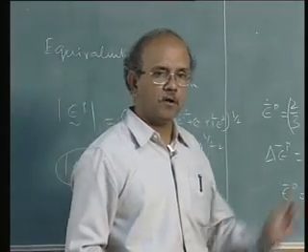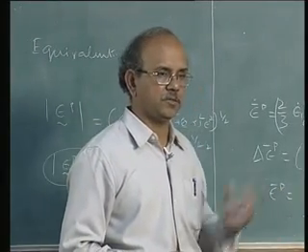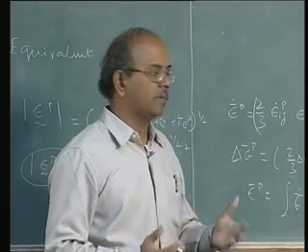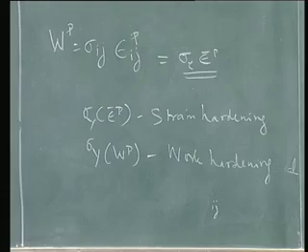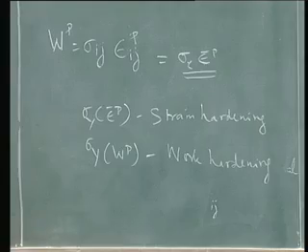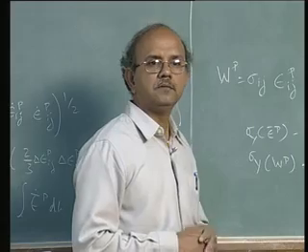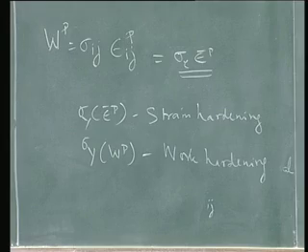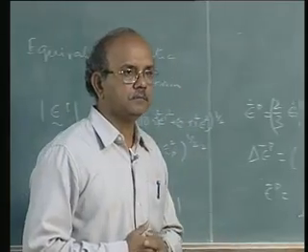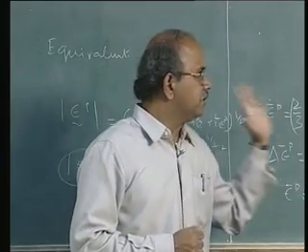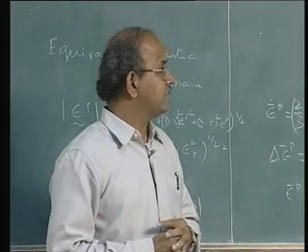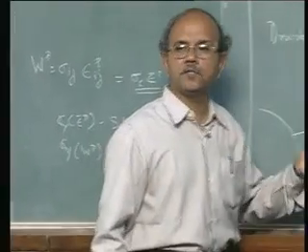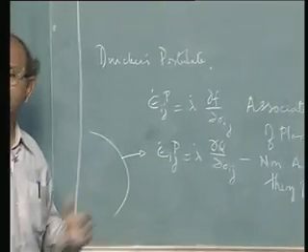But fortunately for the Mises criterion materials, which we are going to concentrate on extensively in this course, both of them happen to be the same. The results that we are going to obtain with either strain hardening or work hardening are equivalent. Having studied that, and having now completed all the things that are required, except for a few comments, we are again coming back to Drucker's postulate, which should be in order to study further.